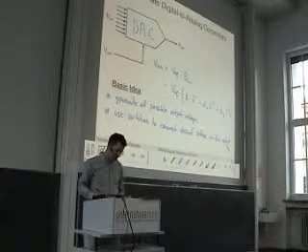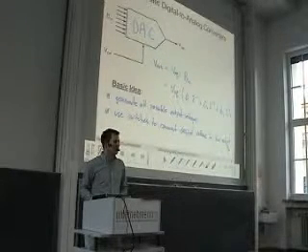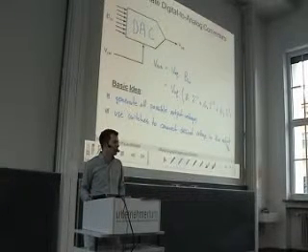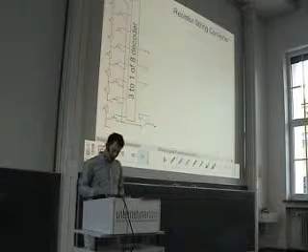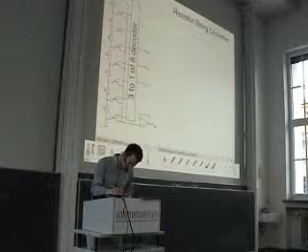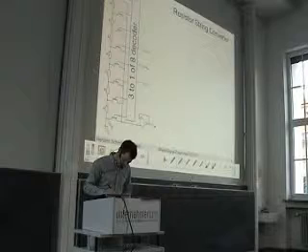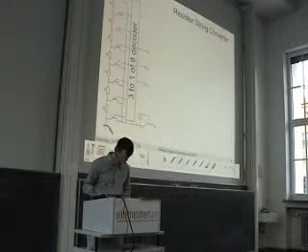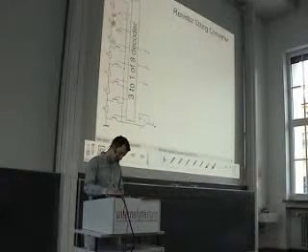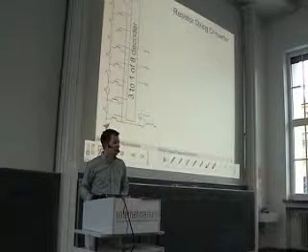If you think back to one of your basic courses, then one of the first circuits you saw is the resistive voltage divider. And of course, this is what we can use to generate all these output voltages. So in this circuit, we have first a reference voltage here. Here we have a ground signal. And then we connect this string of resistors in between Vref and ground.